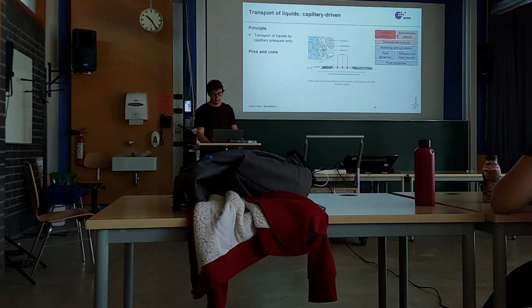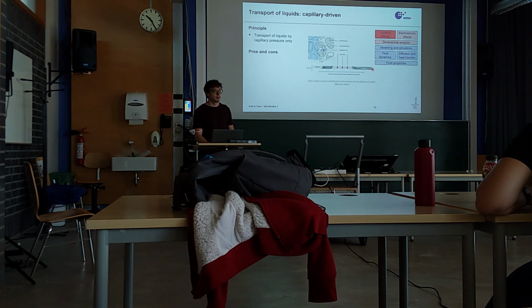So obviously, all you need basically to understand the propulsion force here is the surface effects lecture, because the liquid is purely transported by capillary pressure. And the most prominent example where this kind of technology is used are lateral flow stripes. And they make use of it by